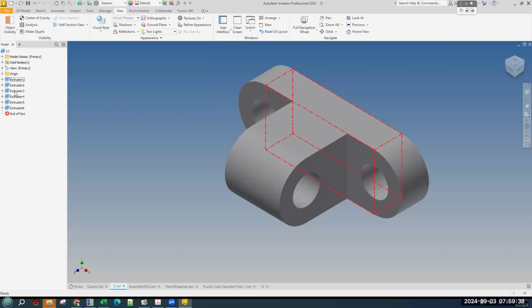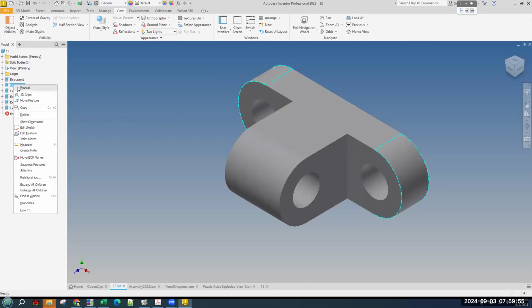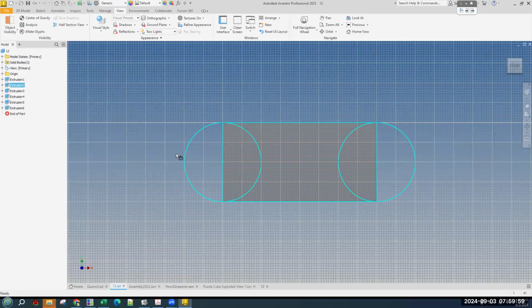This is critical. This is like the history of the shape, or like, you know, undo. The problem is if you have something complex and you want to change the second of your 6 different part features, you can't just undo one of them. It would undo everything, but you can go back and edit different portions of it. Like, well, this one's all constrained.